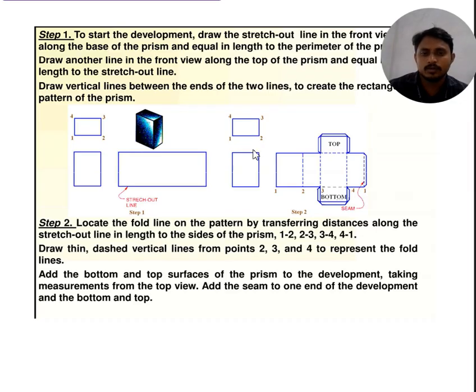If it is a top view, draw it on the horizontal plane. Front views are drawn on the vertical plane, and top views on the horizontal plane. For the rectangular position, if you take 6 centimeters, draw a 6 centimeter distance as the height or the axis height.